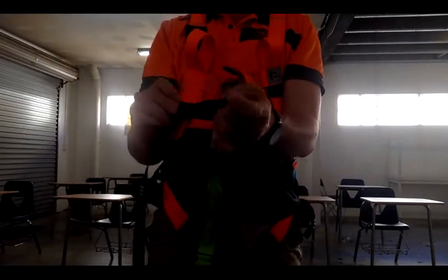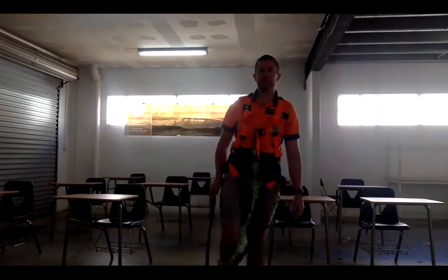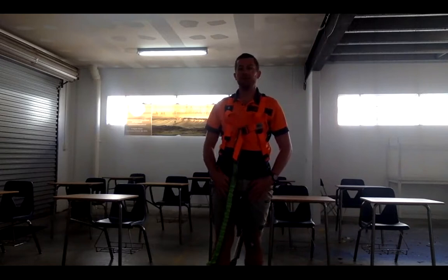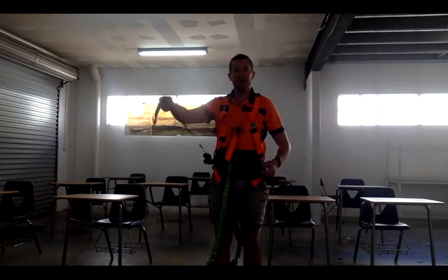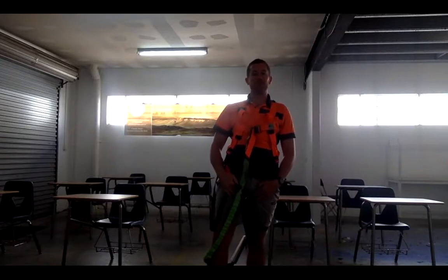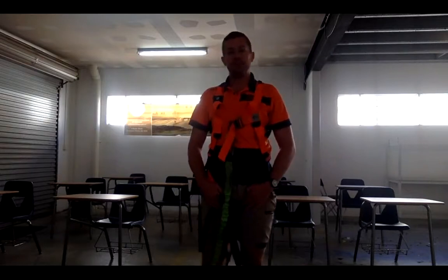Once it comes out, make a loop in it itself, and I can now put my foot in there. Once it's hanging down beside me, I can put my foot in there and stand up in the harness and take the weight off my legs. So if I'm still hanging there and someone can't get to me within 5 minutes, I can effectively self-rescue because the pressure is off my legs, and I can stay suspended, standing up, as long as it takes for someone to make the rescue.